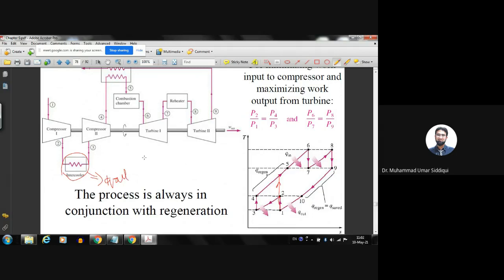Q out. Now this heat rejection process takes place at constant pressure, and then we make the air pass through the other compressor and do the rest of the compression. So what we have done is that if we look here in the TS diagram, we have added this area to our net work. This area would not be there if there was no intercooling, but we added it with the help of intercooling. Increasing the area under the curve means increasing the net work. So we are actually increasing the net work by doing the intercooling.